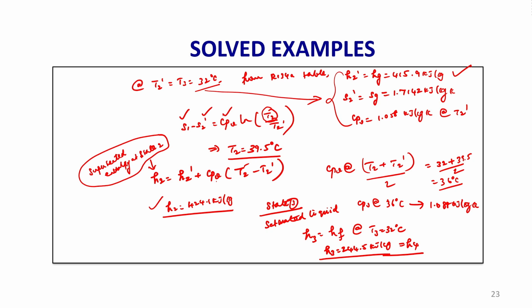So, to summarize, we have seen the reversed Carnot cycle, which forms the basis for the ideal refrigeration cycle, where in the expansion process the turbine is replaced by an expansion device, whereas the other processes, compression, heat rejection and heat addition, that is evaporation and condensation, are the same. So, with this let me conclude lecture number 20.